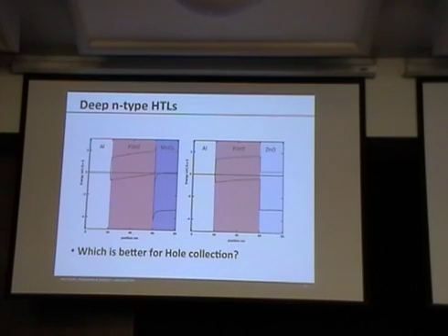That's the simple definition. If I make a contact at that interface, or in that region of the interface, although now we're recognizing that that may consist of most of the device, in such a way as to enhance the extraction of holes out of that side, I've basically improved my device. And I think if you look at the device physics in total and think about things like quasi-Fermi levels and other things that people talk about, it all boils back down to this notion about how fast you are removing these charge carriers versus how fast you are allowing them to recombine.